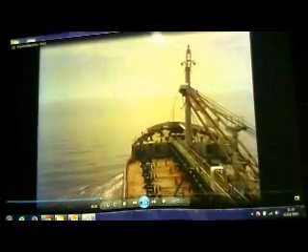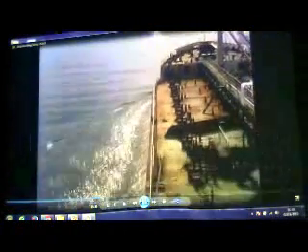A ship moving through the water tends to drag some water along with it due to skin friction. This is known as the boundary layer and can be seen on the surface close to the ship's side. Below the surface, the boundary layer will affect a considerable portion of the propeller disc. At cross-section level with the propeller, the rate of flow is represented by a darker blue for a reduction in flow rate. This is known as a wake diagram. This example of a single screw ship shows how much of the propeller is affected. The darkest blue area represents a reduction in velocity of 80%.